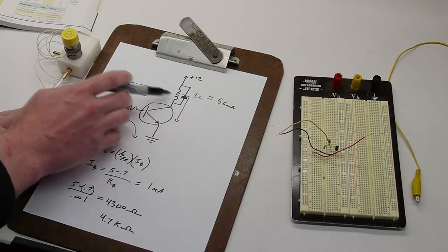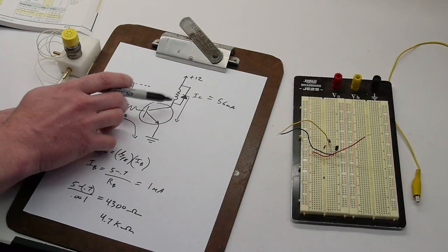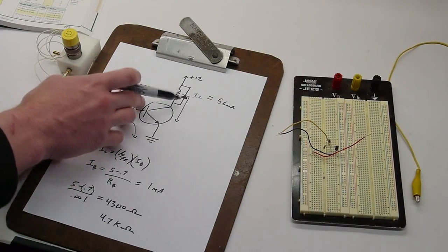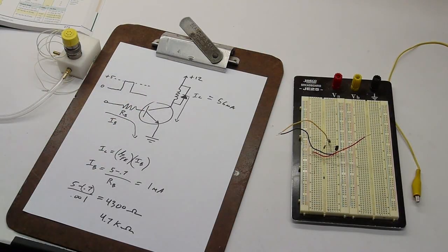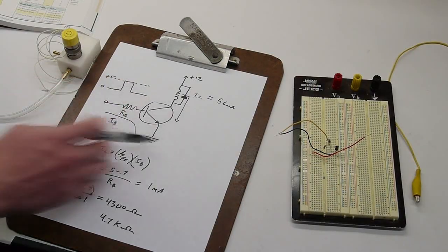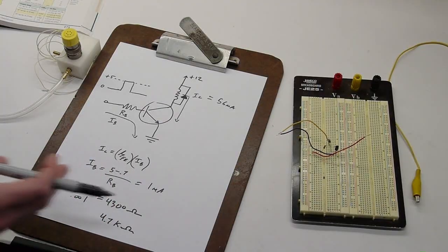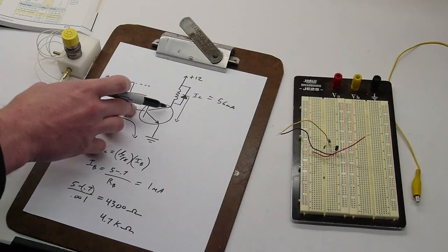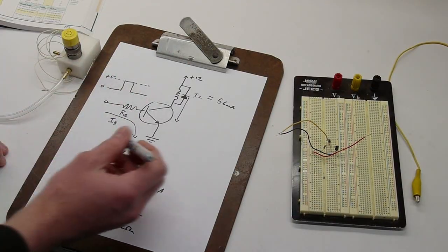If the coil has a lot of inductance, the voltage could get to be hundreds of volts here, high enough where it would actually blow out the transistor. So it's extremely good design practice to put a clamp diode in there. It could be a real problem because you might design this and switch it 20 times on the test bench and it works fine. And then you go out and put the circuit into service and it switches and it gets to be just high enough and it blows your transistor out. So definitely put a diode there.